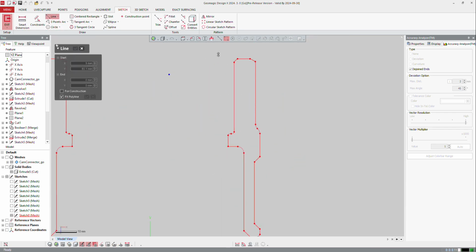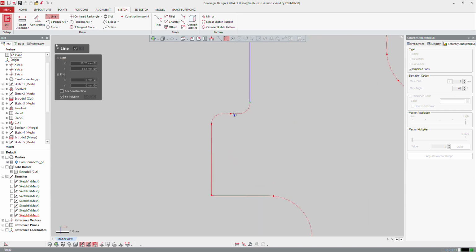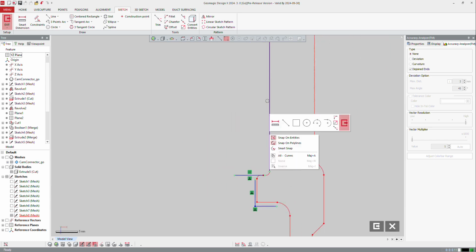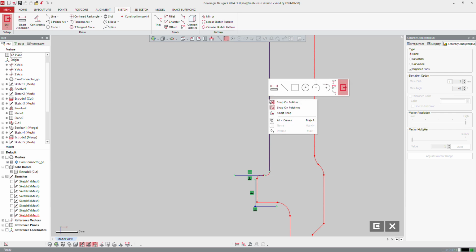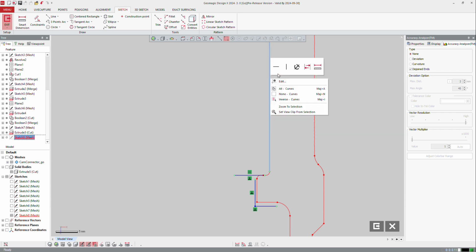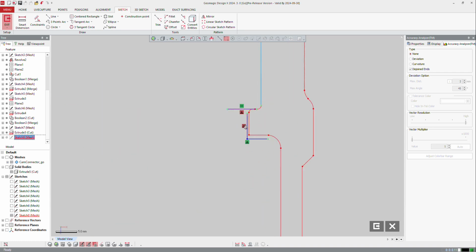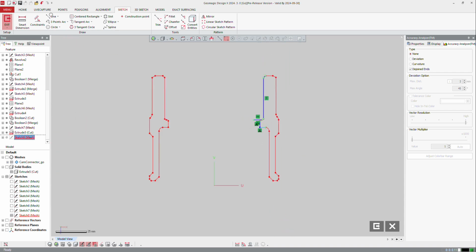So let's go line and create my curves. So that one is not right. I will take one point and move it out to get horizontality. And again, you can create by double clicking or by just clicking like that, you define horizontality and verticality. And otherwise, you have to do it afterwards, like right mouse click on the line and verticality. This one got angle. And if you do it for outside, you need to remagnet the curve.